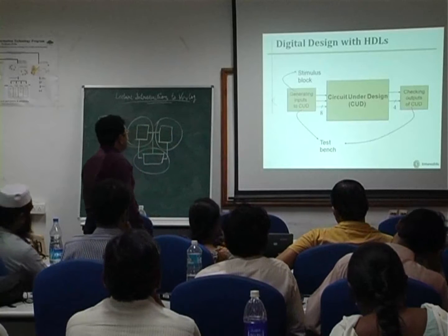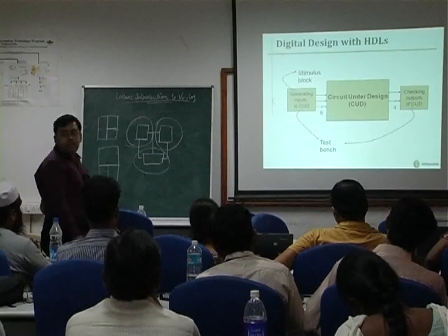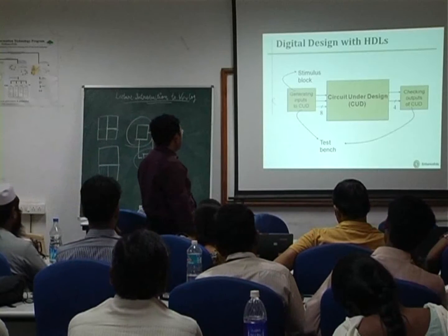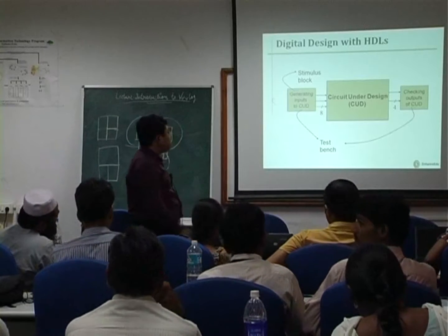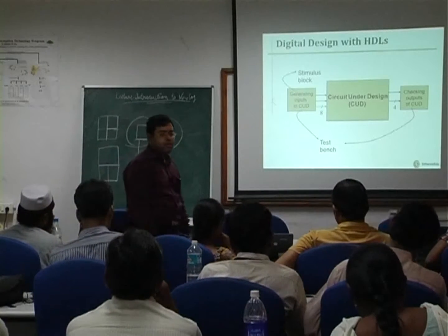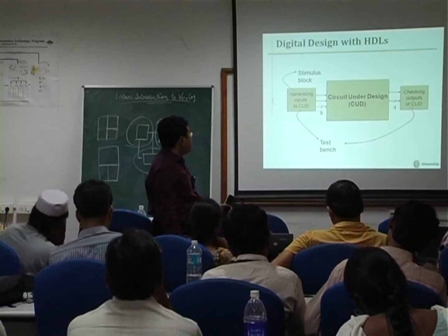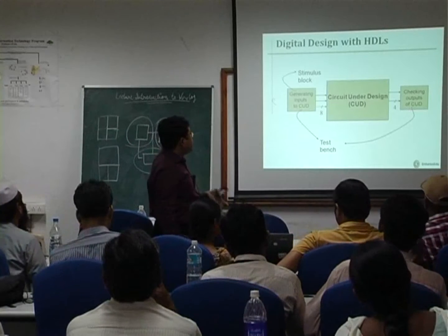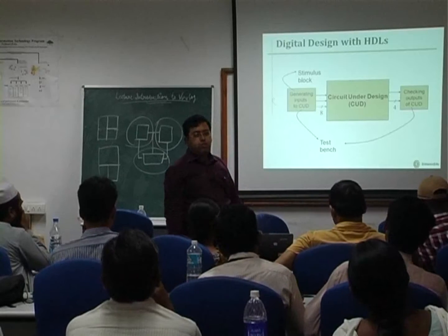If you look into analyzing circuits with the help of hardware description languages, we use a stimulus generator to provide certain inputs to the circuit under design and check the outputs of the circuit. So we use a test bench to generate the stimuli for the circuit under test and check the output.